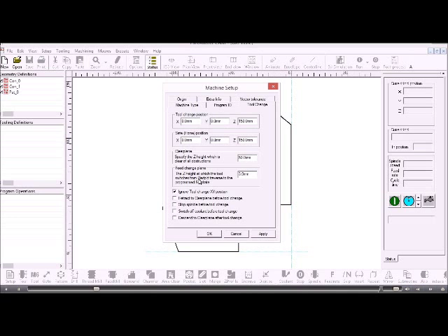On most modern controllers now, doing things like an M6T1 will switch off the coolant, stop the spindle, invoke the tool changer and so on. But on older machines you may have to manually intervene and have different M codes to switch the spindle off. If you need to do any of that, this is where you can use the check boxes to do that, but in most cases this is no longer needed.